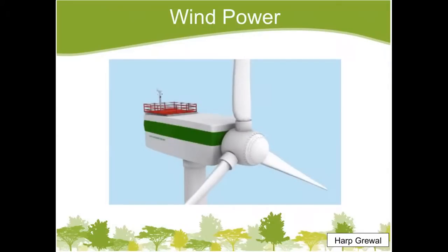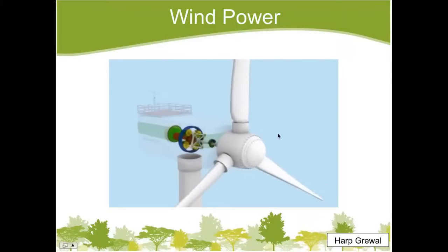Here what you see is a wind turbine. It's connected to a body, above which is a weather vane, which points the turbine into the direction of the wind, directly facing it, so it has maximum power output. Now inside of the body of the turbine are mechanical gears, which are connected to a generator. Since the blades of this turbine only spin at roughly 20 RPM, the gears inside make the generator turn much quicker, up to about 2000 RPM.